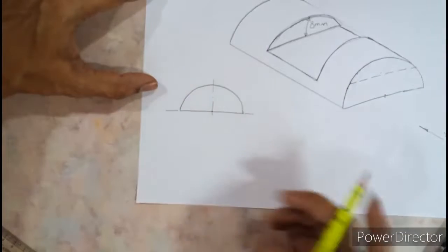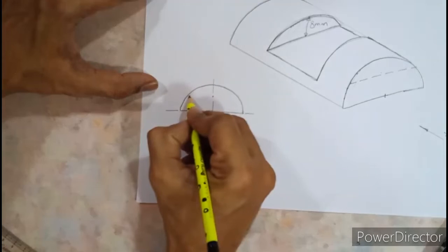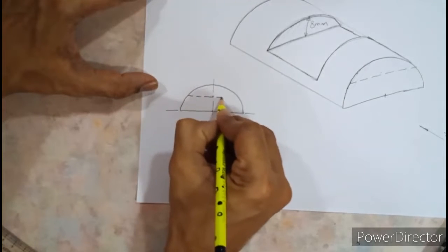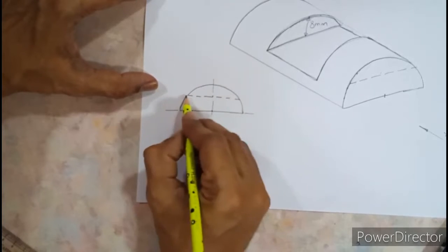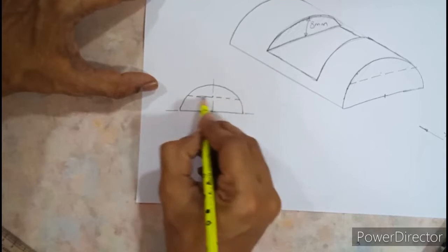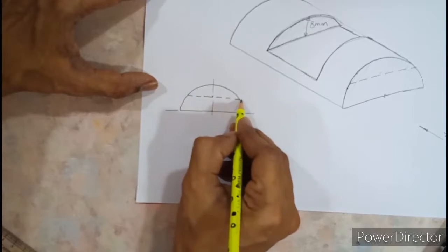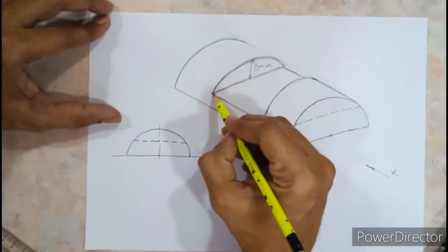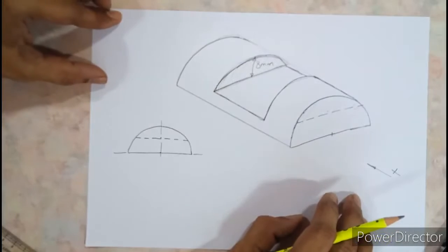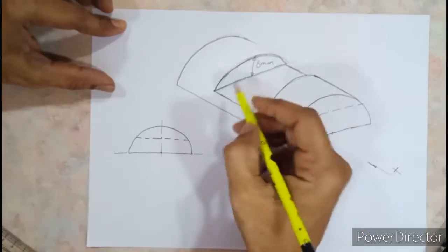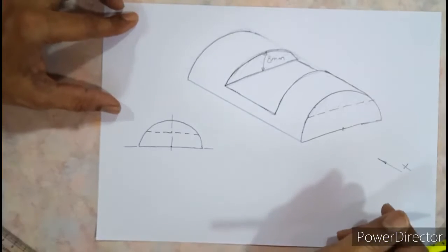So in this diagram, when you draw the hidden line, you need to come from the top portion by 8 millimeter down and draw a horizontal line, double trace, to cut the semicircular portion. The length of this line can be determined only after drawing a horizontal line so as to cut the semicircle. Wherever this line intersects the semicircle, that length is the same as this edge. There are many things in engineering graphics which can be understood only after you draw. You cannot apply mathematics over here. So that is how the front view is ready.